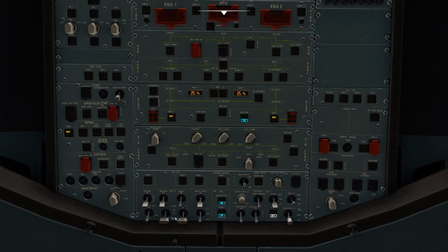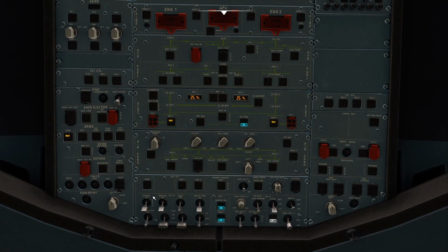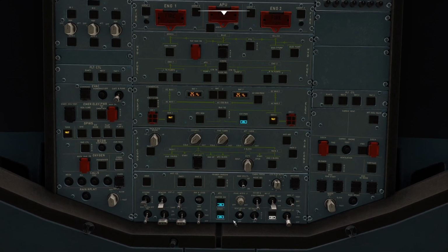In this, let's say, cockpit preparation phase, right now you will only need the strobe lights and nav and logo light to be on. Seatbelt signs and no smoking signs are compulsory actions to be switched on in this phase. And then don't forget to set the emergency exit light to arm. With that, the overhead panel is all done.